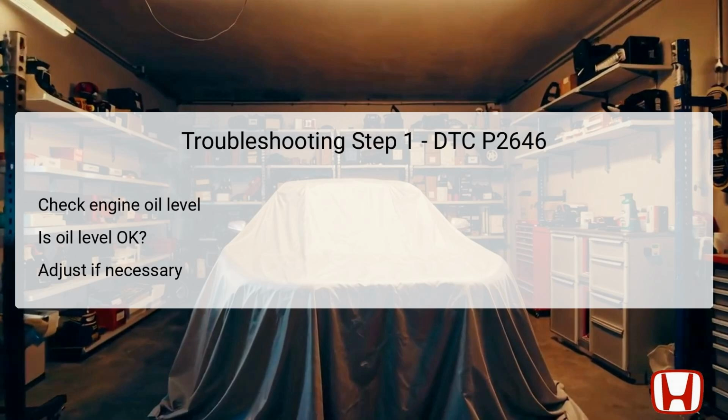the next steps. This adjustment is crucial, as having optimal oil levels is necessary for the proper functioning of the rocker arm oil pressure switch and the overall VTEC system. If the oil level is adequate, you can proceed to the next step to further diagnose the issue.